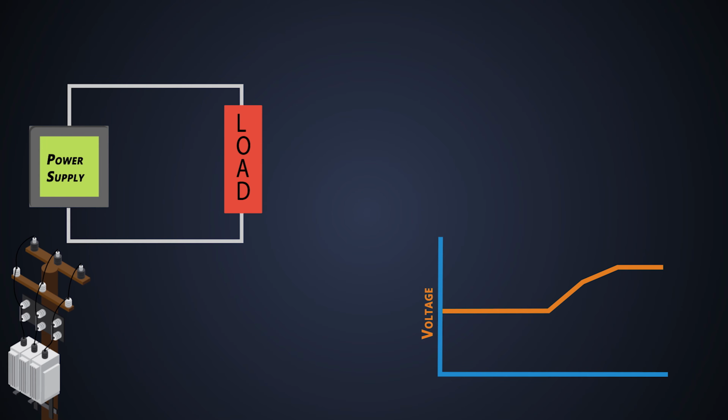In this protection, we have to set a threshold voltage above which the control circuit shuts down the power supply or diverts the extra voltage to another part of the circuit. And we can use a BJT to protect any circuit from overvoltage. This is one of the most important applications where BJTs are widely used.